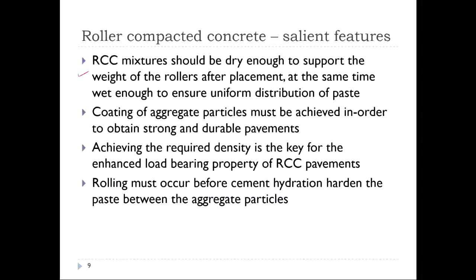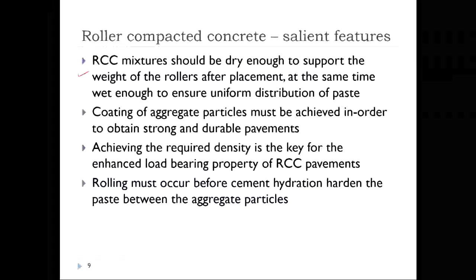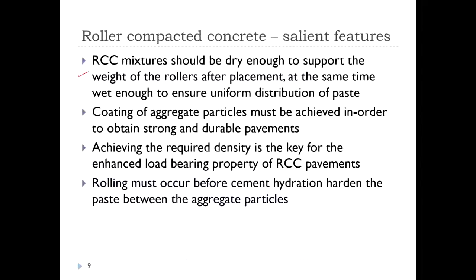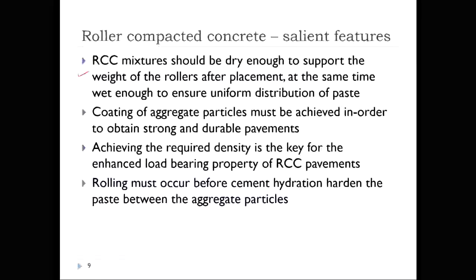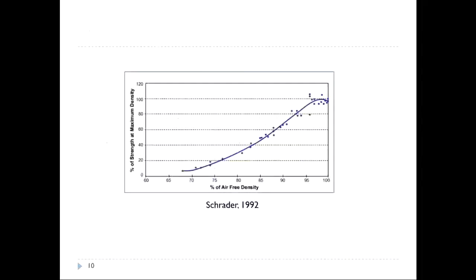Now, in the case of the pattern of rolling, you can start the rolling from the edge and proceed to the interior. The main thing is that, just because we have cement as the binding material, we should start our rolling operation before the cement hydration starts. Because if you don't compact it before the initiation of the hydration process, this would result in the formation of hairline cracks.